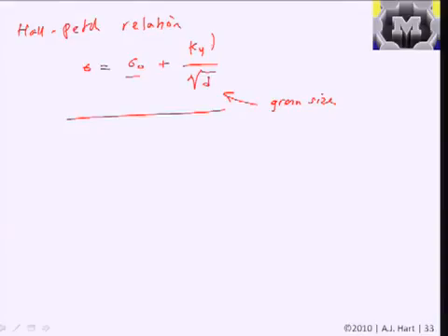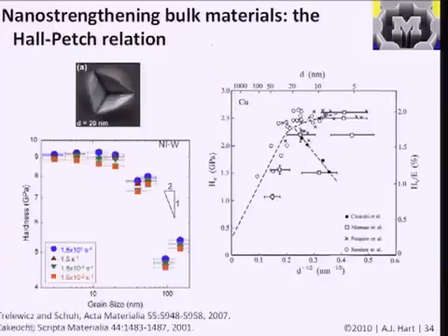But what's happened recently in research is that as we're able to manipulate grain size to smaller scales, we find that there are some interesting and complex trade-offs in the characteristics of the material. So people have studied this for different metal alloys. This just shows nickel and tungsten and copper. Basically, now that we're able to control the grain size of these bulk materials down to regimes of, say, tens of nanometers, we're finding that there's a lot more opportunity to engineer the properties, but principally this idea of grain size strengthening breaks down, because you can have more slip between the grains, and also because of there being so much surface. Imagine the material is like a whole bunch of nanoparticles pressed together. You actually have more diffusion of the atoms under deformation.